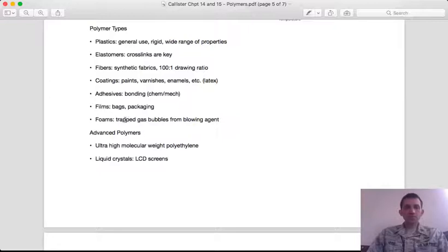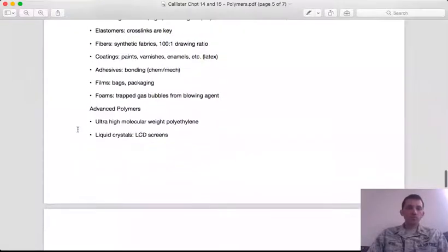And if you trap those gas bubbles, then you can form pores and voids inside of the polymer, which reduces its weight considerably and can increase its insulating value, those sorts of things. You can either have gas that's produced as a part of the chemical reaction, or actually dissolve the gas into the resin system, and then later draw that gas out under vacuum to create the bubbles.